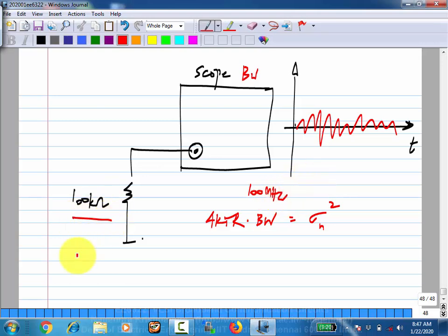What is the noise spectral density of a 100 kilo ohm resistor? 4 nanovolts per root hertz. No. 40 nanovolts per root hertz. And this has to be multiplied with how much? Square root of the bandwidth. Okay. So how much is that? What is the square root of the bandwidth? 10? Okay, so what is sigma n? Yeah, it's 400 microvolts or 0.4 millivolts.